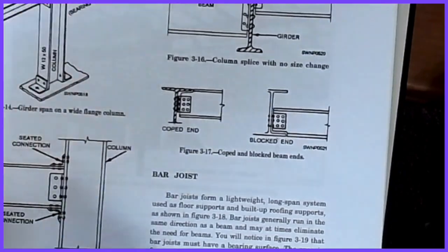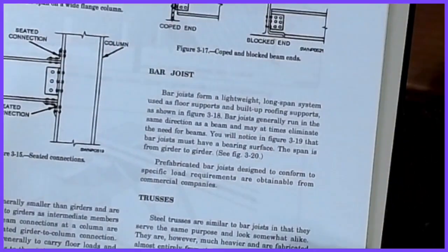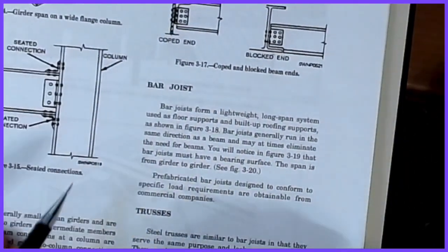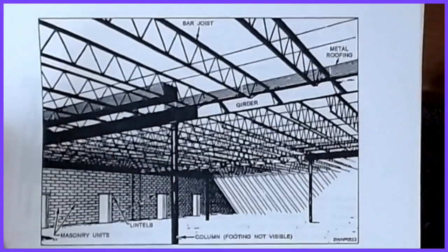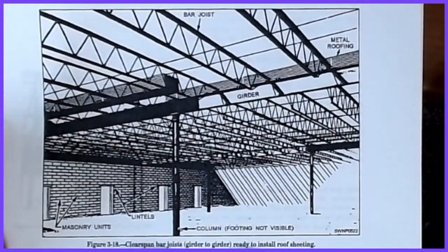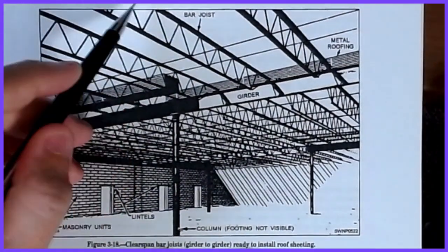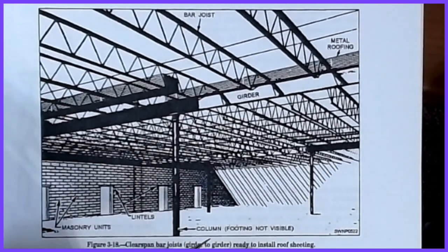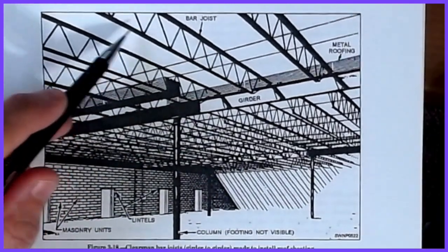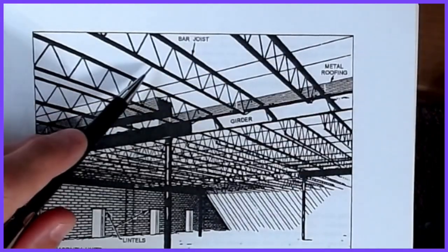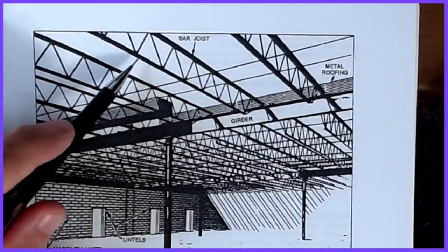Another type of connector piece that you'll hear the term for is bar joist. That's basically called an open web steel joist, and these are the truss guys. If you walk into a Walmart or a Home Depot or something like that, these are what we're talking about as far as open web steel joists or bar joists. And these are nice. They're very lightweight. They're prefabbed as a unit, and then you basically pick up the whole unit, and they're trusses. You basically preset them.